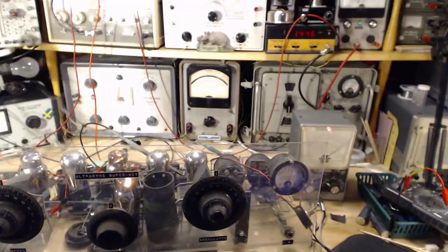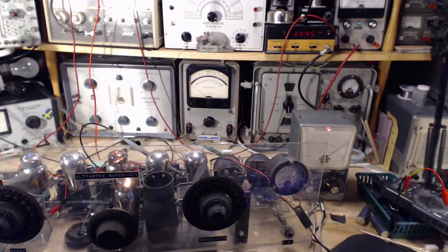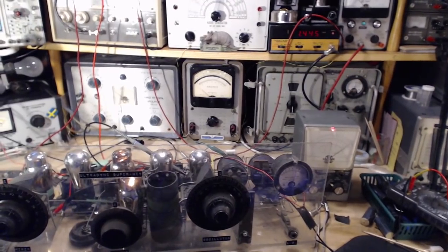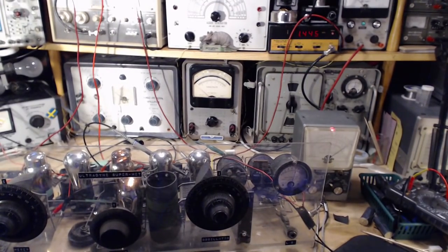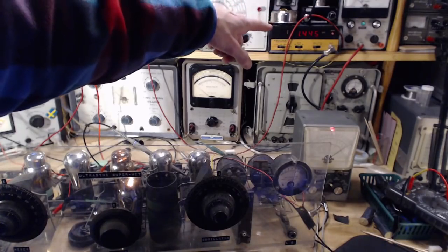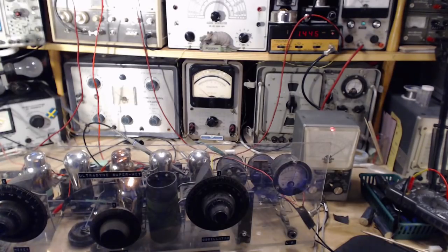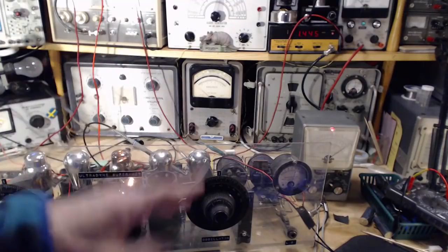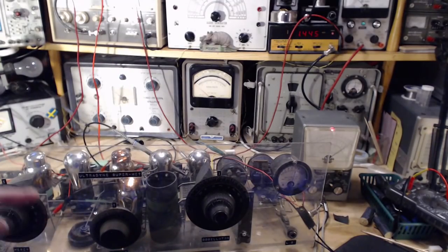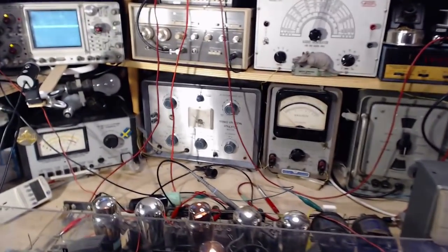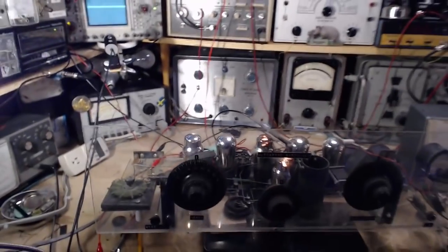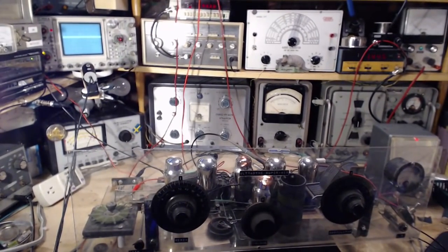Okay, that's pumping out a fairly strong signal right now. And what are we getting? There's nothing on the scope. So we're way up at 1400 kilohertz. We really want to be trying to feed, assuming the oscillator and all that stuff is not really working, we really should try to hit this with the IF frequency itself. And then watch to see what happens on the scope if I hit it.